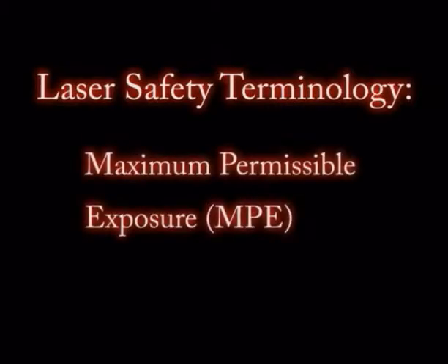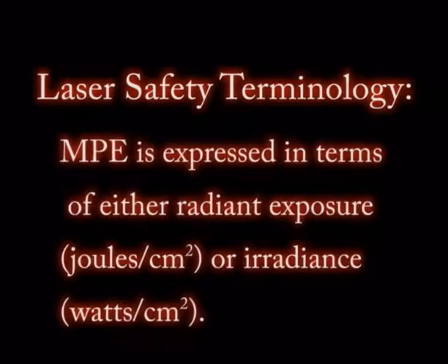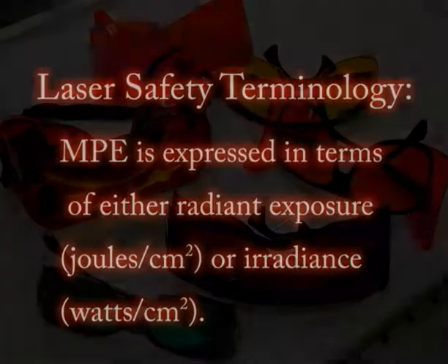Before we begin, it is beneficial that you acquaint yourself with various laser safety terms and regulations that govern laser products. When we speak of safe viewing of the laser beam, it is in terms of MPE or maximum permissible exposure. This value represents the level of laser radiation to which a person may be exposed without hazardous effects or adverse biological changes within the eye or skin.